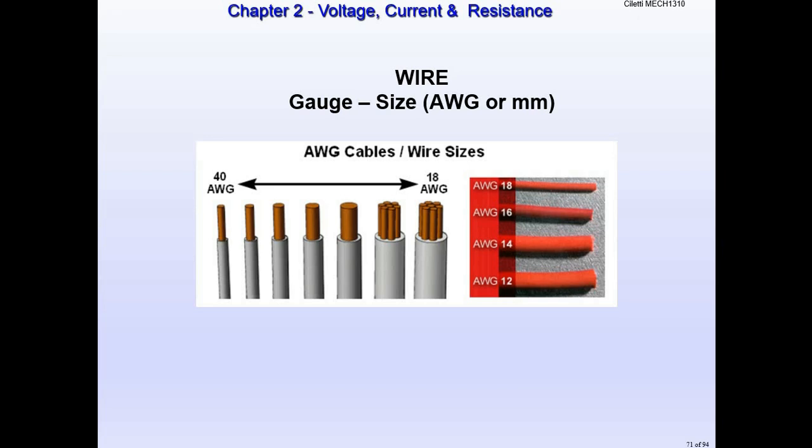How much current is the motor going to draw? All right, so if you have a hot tub at your house, you can't use a 2-conductor 14 wire. You have to raise to a number 10 size wire. You need a larger wire to run 30 amps. All right, you might have to run to like a size 8 wire to run 60 amps. So the more amperage, okay, the larger size wire you're going to need for multiple reasons.